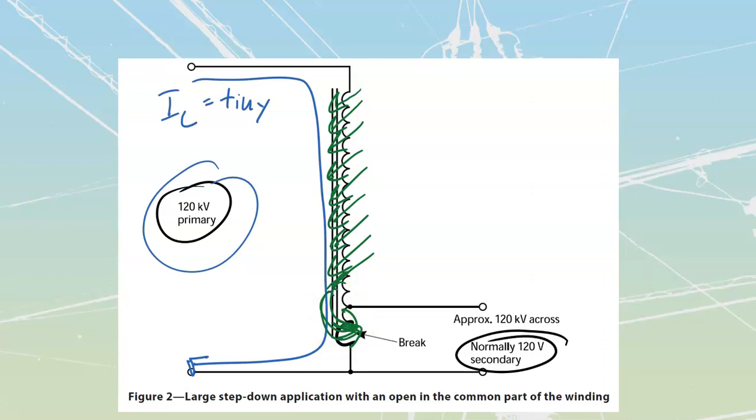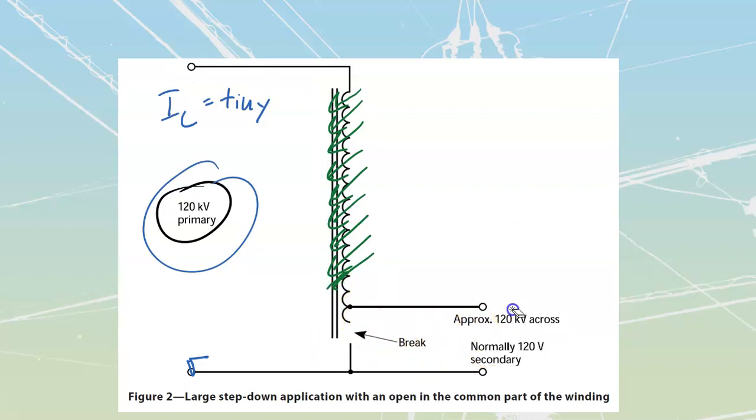So under ideal operation, I'm going to have a low value of voltage coming out here, but a really large value of current that I would be able to put out from here, just due to the transformer action itself. This would be the way it would normally operate. I'm going to have counter EMFs in here that oppose the flux inside here, and so this whole system works in balance. But as soon as we go into a break over here, all of that shuts down.